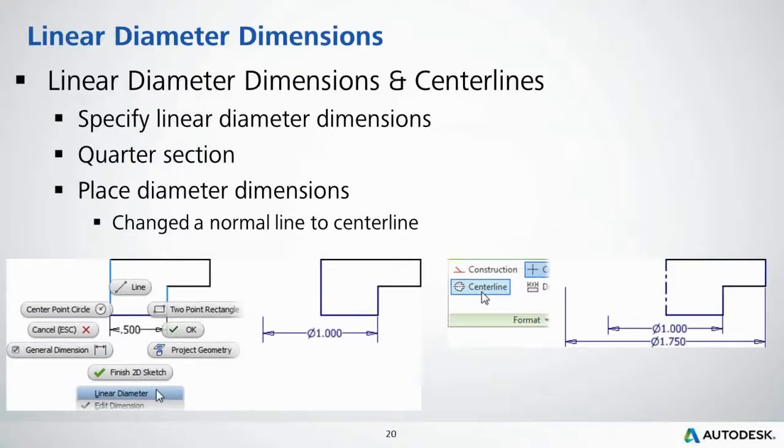Before doing a revolve, one thing that we're going to need to do is sketch out our geometry, and when we sketch a geometry to do a revolve, we're going to sketch out 1/4 of a profile. So in an example that I'm going to do here in a little bit, I'm going to do a profile, and you're going to see that I'm only going to be sketching 1/4 of that profile.